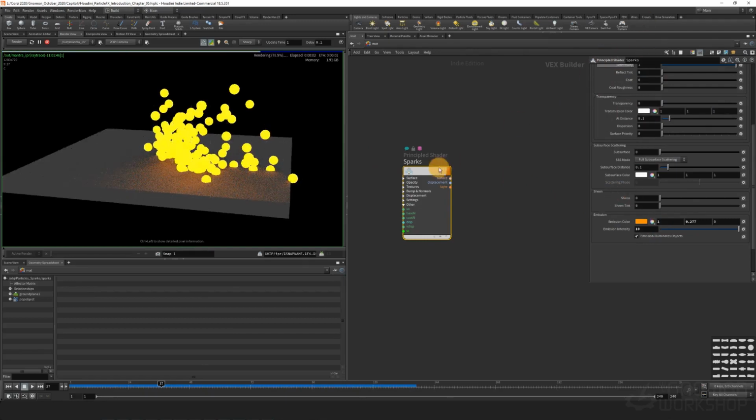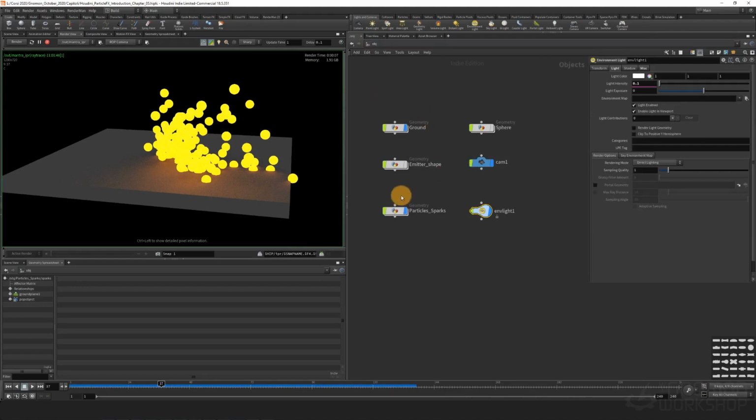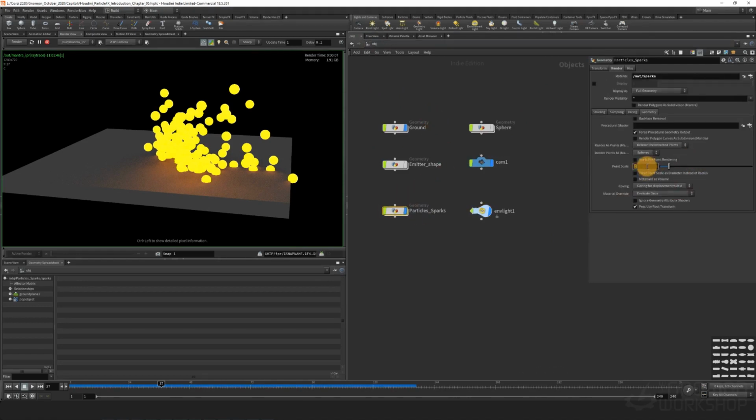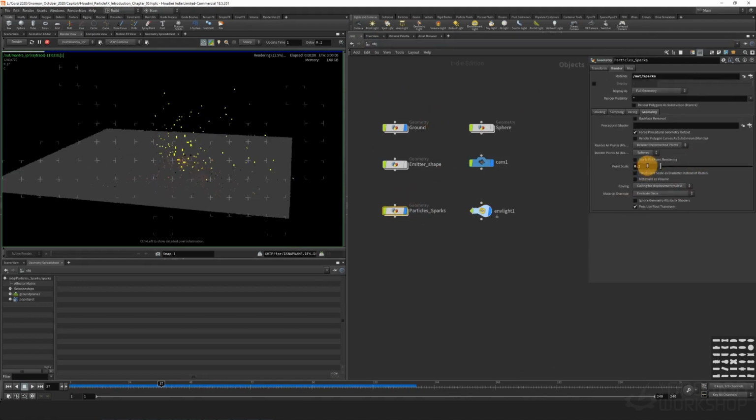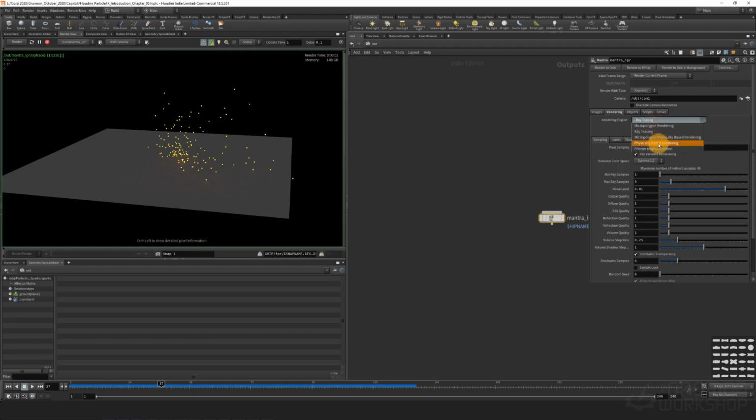so it's really high. Okay, back in the output, we have to take care about the scaling there, so the object, sorry. Okay, in the particles part there, we go for point scale to 0.1. So you see that we are talking about really small scale particles, and that's nice. And about the output there, let's go for the rendering, and let's say that we have physically based rendering.